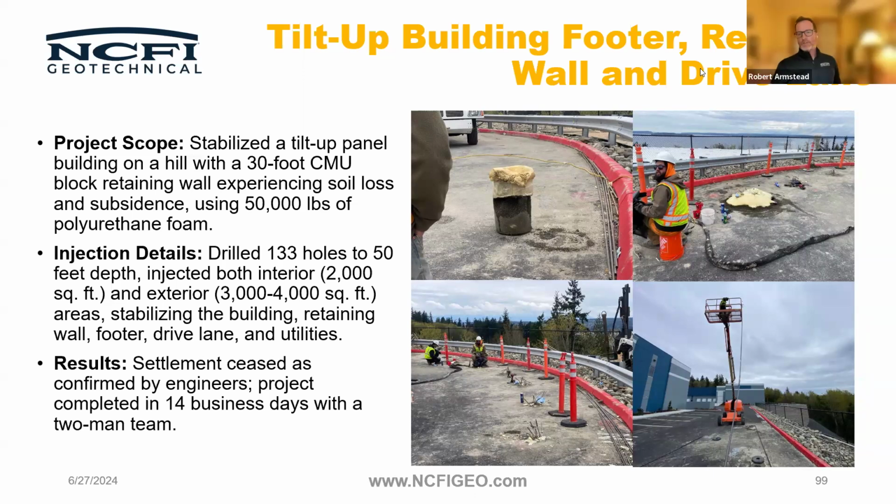As far as a no on material, I would just say maybe a no at the timing. You start getting expansive clays that are really saturated. You probably want to be really careful about treating those, especially expansive clays that have really retracted. You start putting a bunch of material down in there, that clay does come through an expansive process, you might have a problem. So that's all I would say.